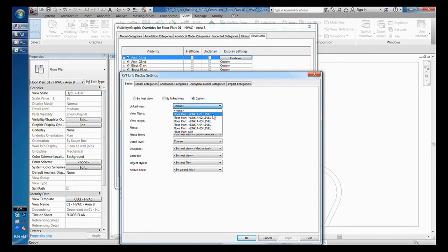My new concept to Mr. Architect is, we'll let you show us how you want your design to appear. And that is one view per level that you manage. This is where you control your detail line work, you make sure it exists, your hatch work, your grids, and they're in complete charge of it. You know, it's a struggle trying to convince them, but we had a number of them loving it because now they get a way of synchronizing the look of all consultants.